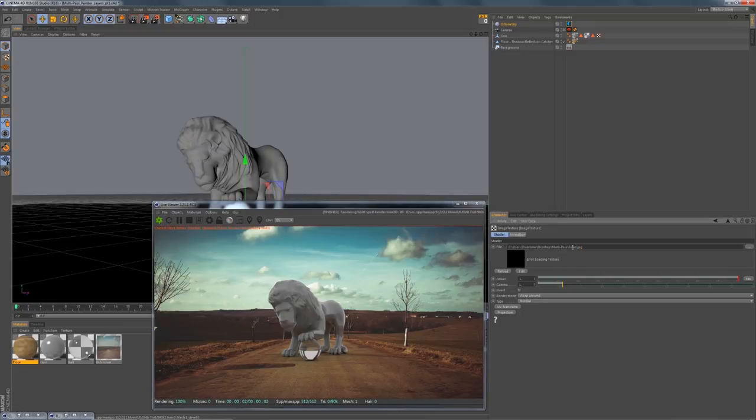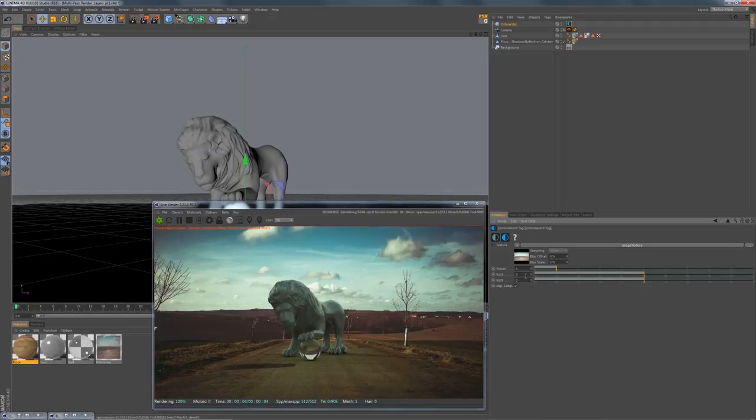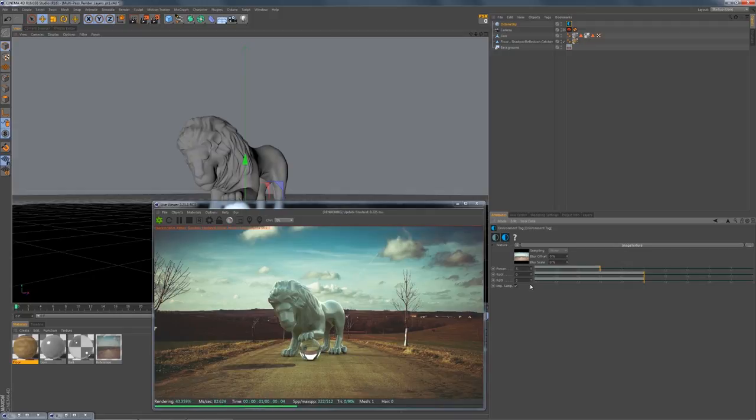If, however, we are using a JPEG, it is a good idea to set the gamma to 2.2. Let's go up a level and probably increase the power to something like 3 and add a rotation of 0.3. Let's bring our panels back up.